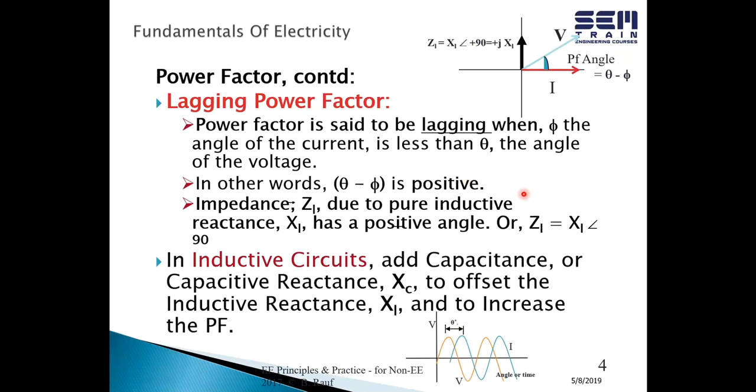And as far as when you have a lagging power factor, how do you remedy that? Because the current is lagging behind the voltage due to the fact that there's an abundance of inductive reactance, you counter it by introducing capacitive reactance.